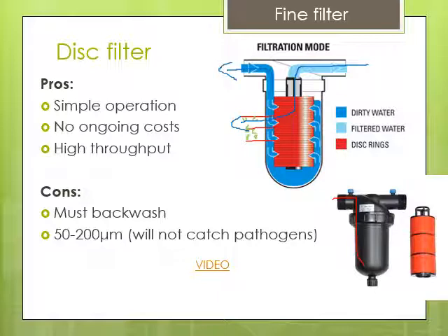So there's backwash. And of course, what's especially cool about this is that the discs actually move apart when you reverse the flow. They open up and loosen, so the debris comes off very easily. Then when you reverse the flow back to normal again, everything snaps shut, the discs all slam together again, and it starts to filter again. So it's a pretty slick setup.